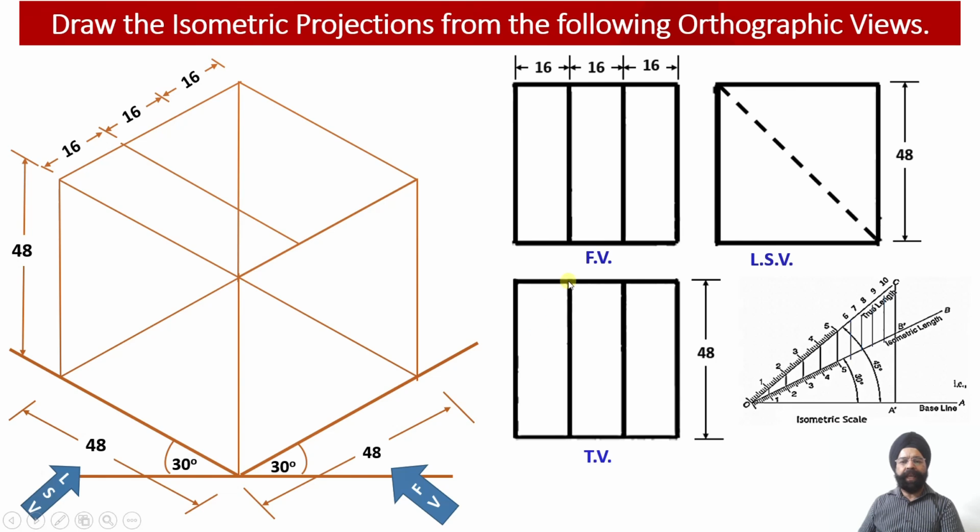As we can see, the length of the external web is 16 millimeter from this end, and another length corresponding to the external web from the other end of this particular solid is also 16 millimeter. So we have marked these two edges over here. Once we draw these two projection lines, please check what we have been able to identify.